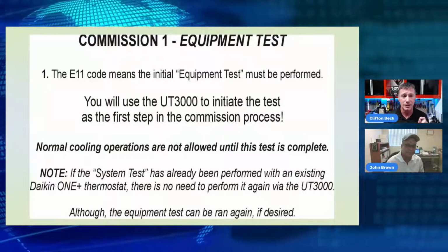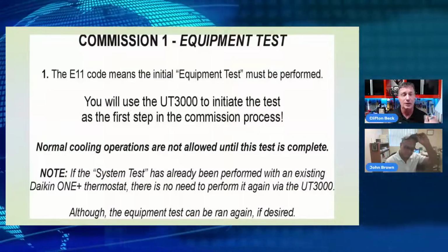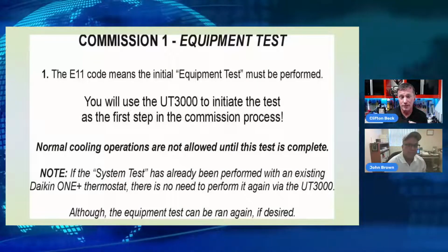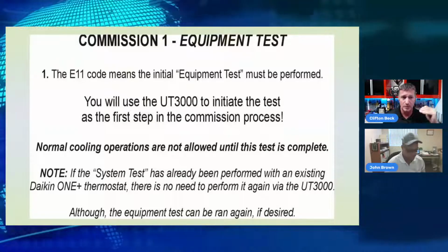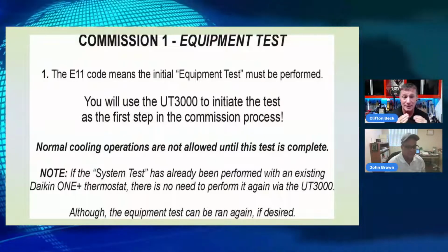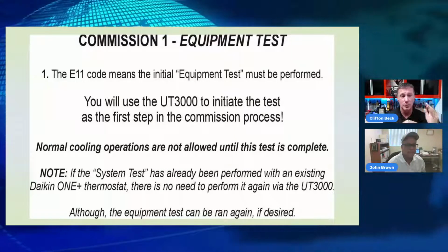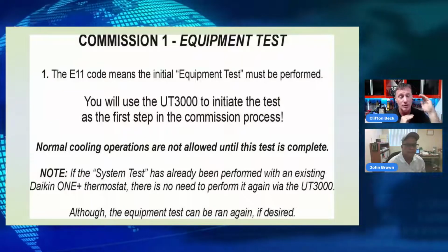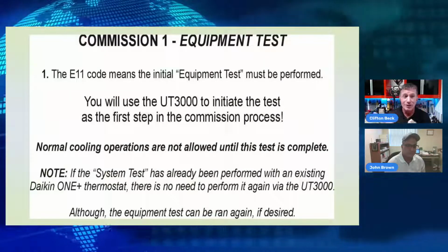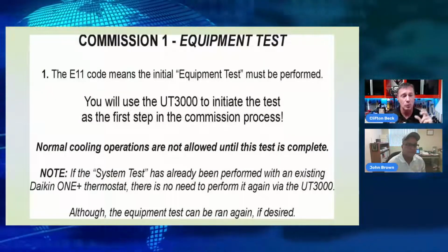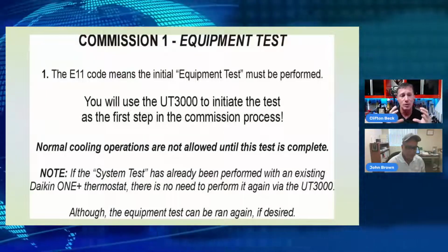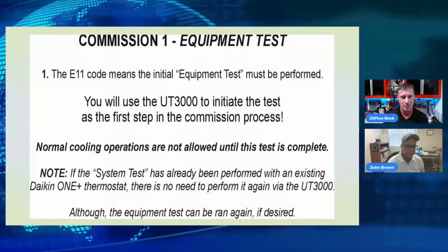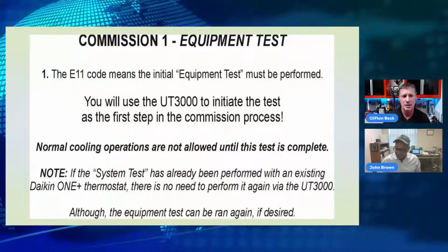If they're doing a system verification test, and this is any manufacturer, we may not start a compressor right off the bat. We may start a condenser fan motor if it's an ECM, so we can vary the speed of it and check amp draws. Then we might turn on a compressor and ramp it around a little bit, looking for different parameters of amp draw. Then we might turn on some airflow and open expansion valves. So we're reading temperatures and pressures to see that the system is compatible and that our capacities are matching properly. So it takes a little while, 7 or 8 minutes on a lot of these.